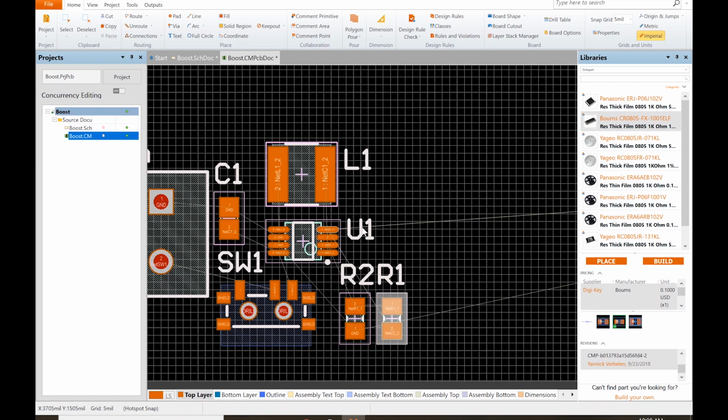So one of the things that I forgot to mention at the beginning is that the PCB design, think of it as layers. So we'll have a double-sided board, but there are certain things like right now we're on the top layer. So all your layers are down here. So the top layer and the bottom layer are going to be where all your copper is, where the traces are, where the pads are. And the through hole, for example, are going to go from one side to the other. Your vias are going to go from one side to the other.